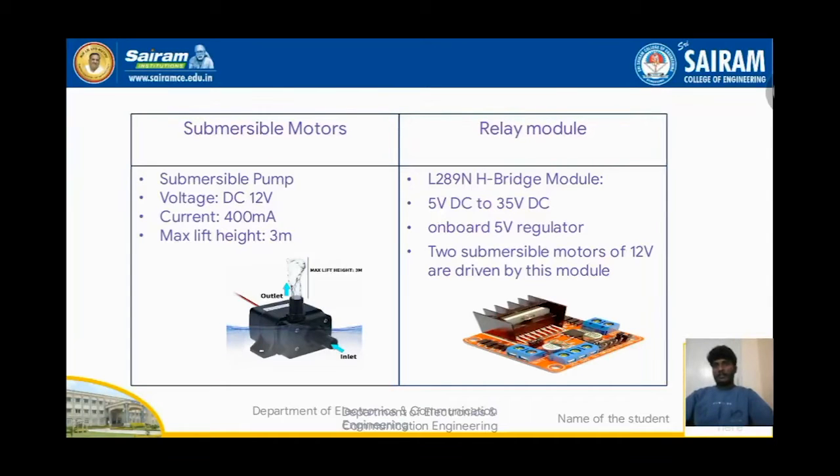The relay module, an L298 H-bridge module. It operates from 5 volt DC to 35 volt DC. The onboard 5 volt regulator is used in this module. Two submersible motors of 12 volt are driven by this module.